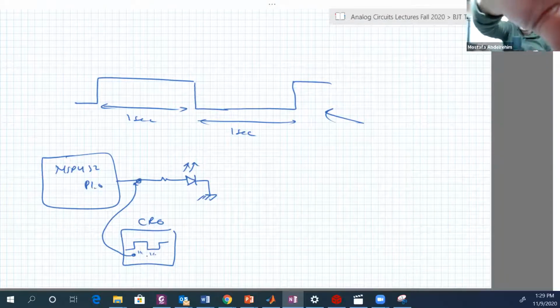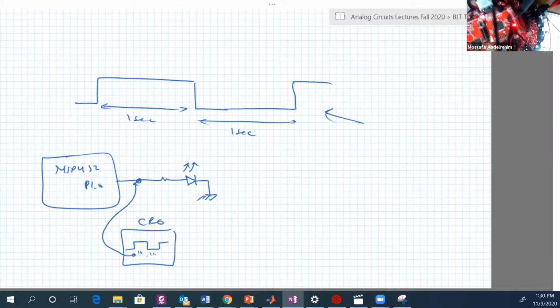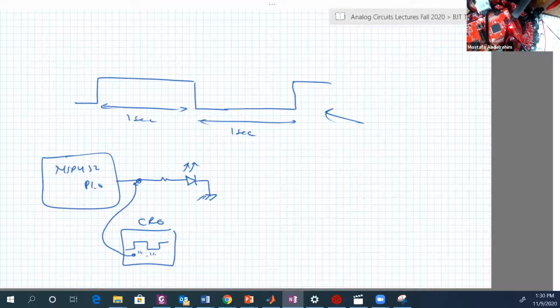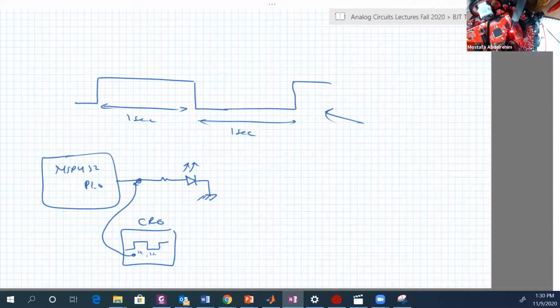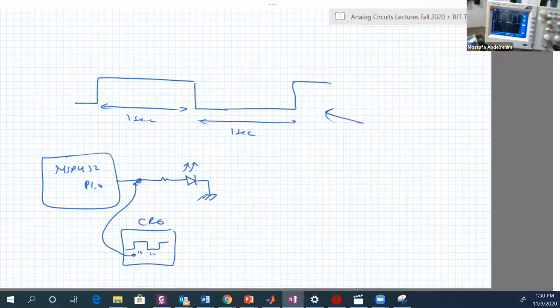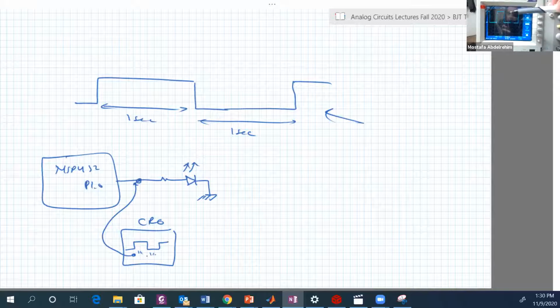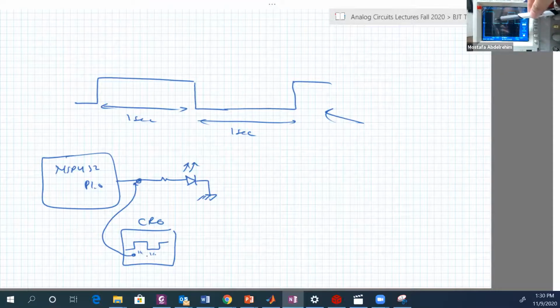So now I'm gonna show you with my camera here. You guys can see, right? If you see the jumper beside LED1, it's written beside it B1.0. So these pins here are connected to B1.0. I put my oscilloscope probe at the metal of this jumper, so it's connected now to B1.0. If we look at the screen, the voltage per division is 1 volt. If we count the squares, 1, 2, 3, 3.3, and we know that the high voltage of this microcontroller is 3.3. Good.